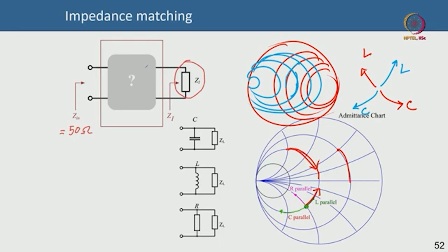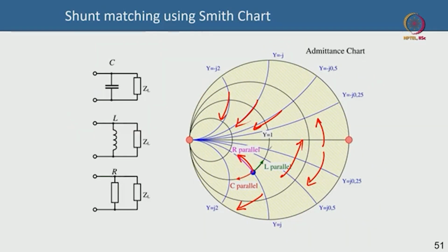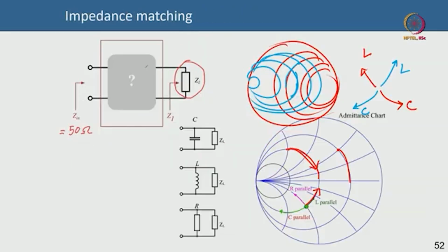And your resistors, which you try to avoid in general, in your traditional Smith chart you will add resistors like that, and in your impedance Smith chart you are going to add resistors like that, okay. So once you are familiar with this movement up and down of adding either resistor or capacitor or inductor in parallel or in series, you can go from any point in the Smith chart to any other point on the Smith chart, and that is the genesis of impedance matching in Smith chart, okay.